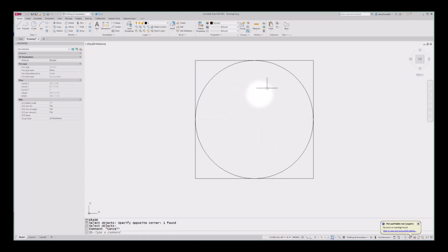All right, now we're going to draw a dial in the middle of the circle. So I'm going to start my polyline command. And then remember, once I touch the edge of the circle with my Osnaps on, it's going to give me the center point. I'm going to turn on ortho and draw a line going to the right. And then I'm going to go up to the top, and it still knows where that intersection and midpoint is, where that circle is touching that rectangle. And then I'm going to get out of that command by hitting Enter or Escape.